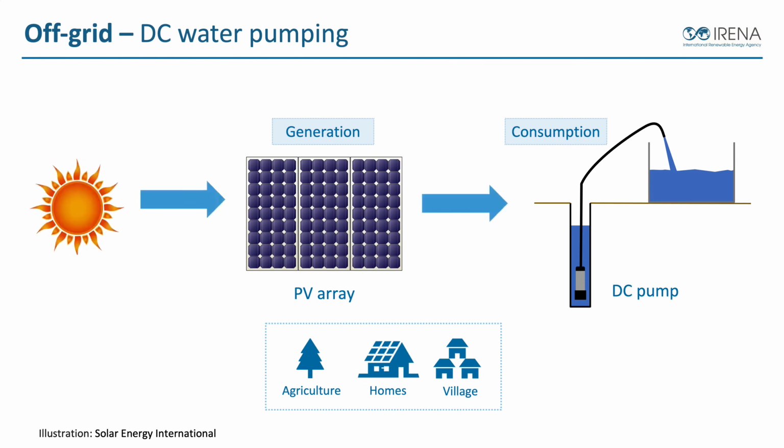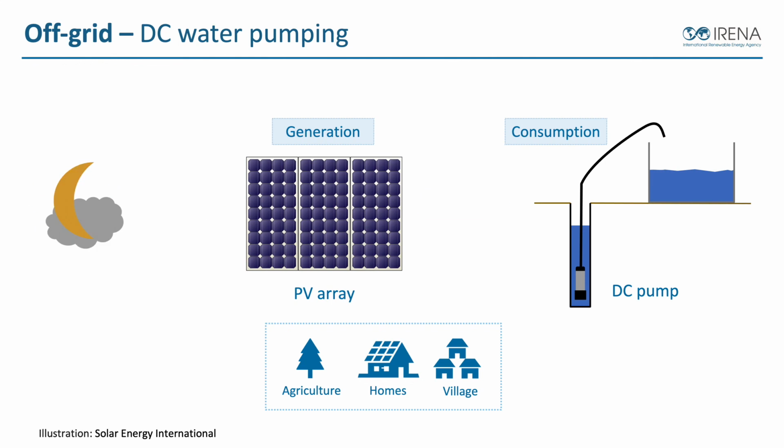So when the sun shines, we pump water, and when the sun sets, we stop pumping water. So this will not pump at night because it doesn't have any energy storage. It's just a daytime only system. So if we were going to use it to run our homes, we might need a secondary pump in order to pressurize a system, or we could pump this water to an elevated tank and use things like gravity supplied energy to pressurize the water system so water could be available 24 hours a day.